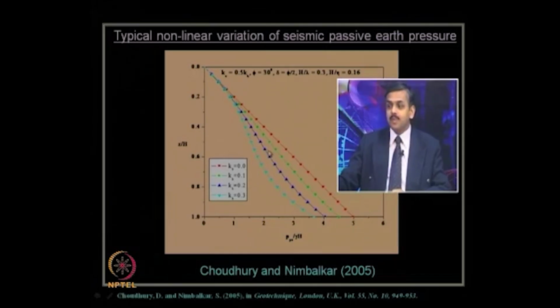and as the seismicity increases, as we know, the direction of the seismic acceleration will act in both directions, whether it is horizontal or vertical, but we have to take the critical value for the design. And what will be the critical value for the passive case? It will be the minimum one, and the minimum one is nothing but it should reduce with increase in the seismicity, right.